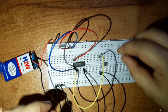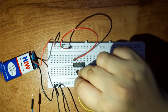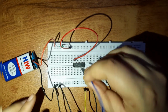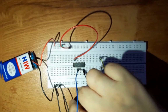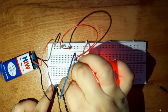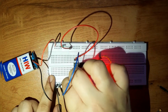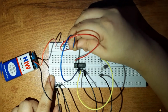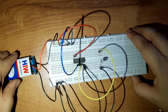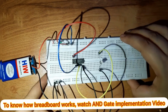Similarly, I can use the next combination of this NOT gate. So I was using first pin as input and second pin as output. Now I will be using third pin as input and fourth pin as output. So you see, if my input is going to be low, the LED will glow, and if my input is going to be positive or high, the output or the LED will not glow. So this is how NOT gate can be implemented using IC 7404.